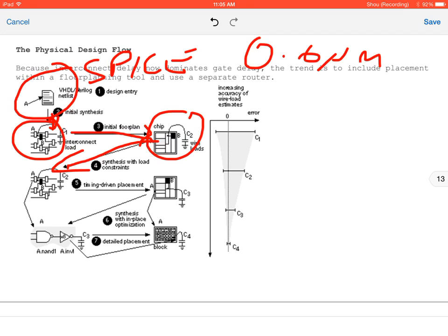meaning that when you're laying out different blocks, you have to ensure that the routing can be achieved in a certain way. We already know about overlapping wires. We already know about, for example, Miller coupling factor. When you synthesize it in a certain way, once you've wired cells together, you limit how they can be laid out.